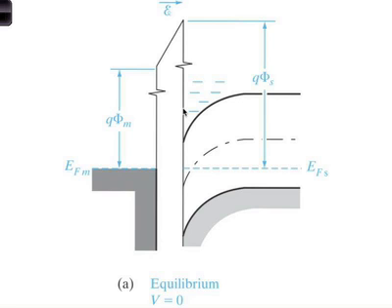You have electrons trapped there, essentially. So it's inverted naturally. This is the so-called device which is always on. And it's also called a depletion mode device because there's a depletion region which naturally exists because of the work function differences. This is a problem, like I said, and we'll discuss this later on.